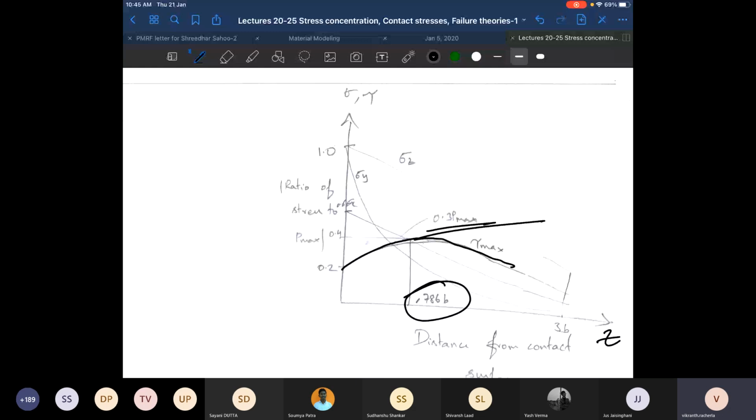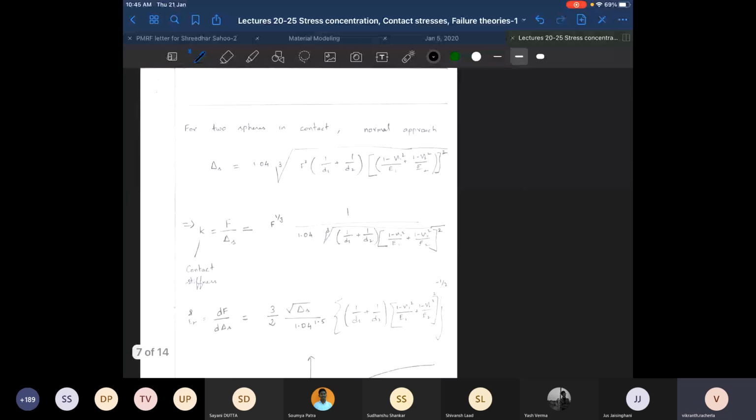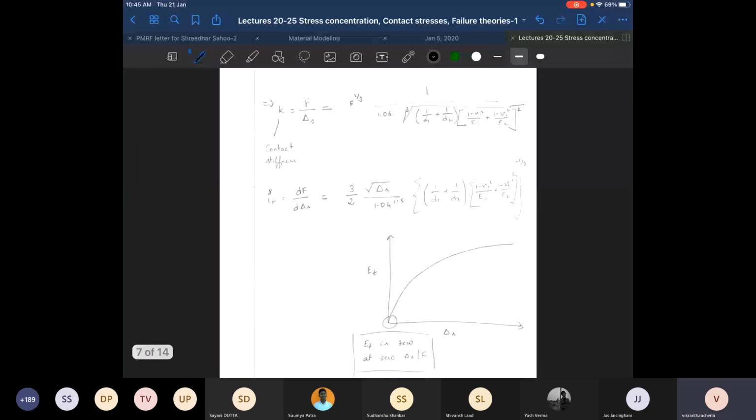This is similar to what you see on roads also. When roads get damaged, you get pit formation instead of surface erosion. So in this rolling contact fatigue failure, what you have is pitting of the material. Cracks will originate from inside and then they will grow out to remove a chunk of the material. All right, I have more things, but let me stop here.